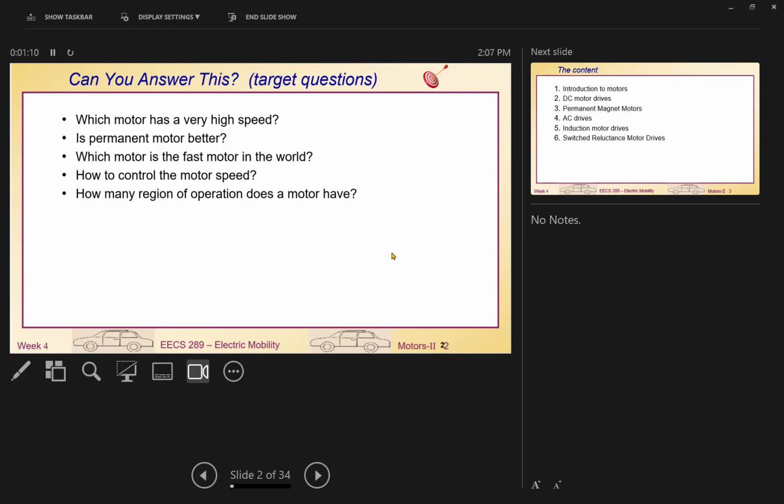Why is that? Because for the switched reluctance motor, there isn't any winding or PM on the rotor. But for brushless DC, we still have the PM in the rotor, which is quite heavy and bulky. Once you have the permanent magnet, you cannot go too high speed. We need a really light rotor to reach high speed. So that's something you need to know. Although many vehicles still use PM brushless motors, the high speed motor is still the SR motor.